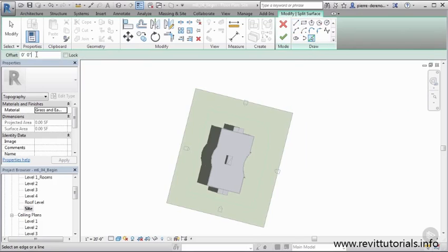And I'm going to apply an offset because I'm going to use these green lines that are in their original position here. Those are going to help me place my trees. And I'm going to want my paving to back up off the trees because I don't want my trees growing out of concrete. So for that reason, I'm going to apply a 10-foot offset. Make sure I'm picking lines, and I'm just going to use these as a guide.